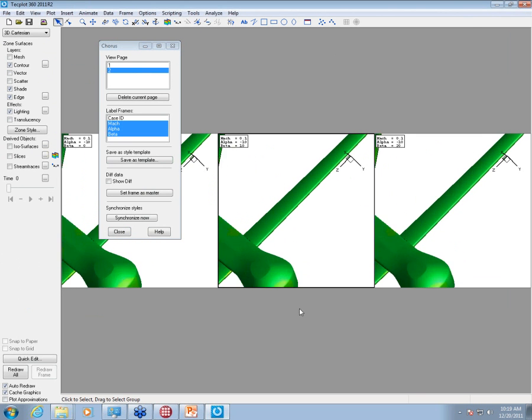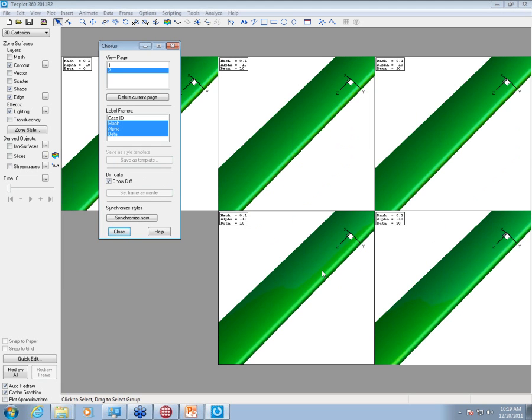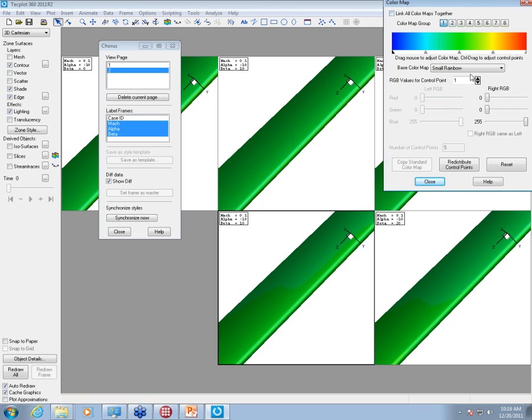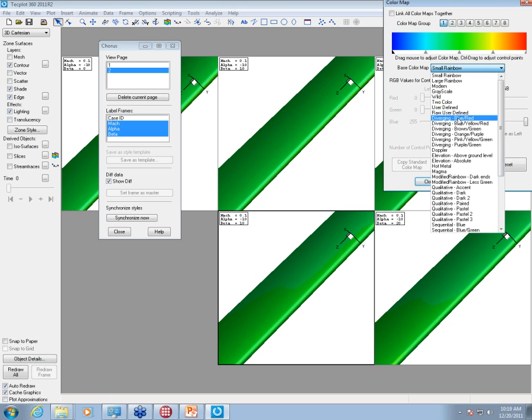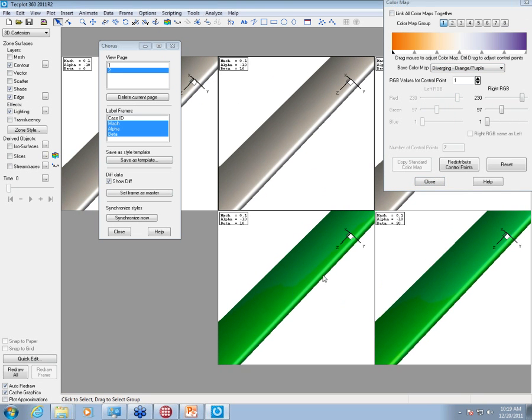If I'm really interested in the delta P right here on the leading edge, I can grab the base case, which would probably be this one at beta 0, and do a quick difference. Now we're looking at a quantified difference between these. You can see it's not that different. I'll change the color map to make this easier to see, using a divergent red-blue. I still can't see the difference very well, but the idea is that if there are large differences, you can pick those up.